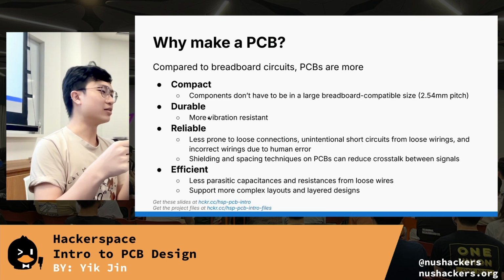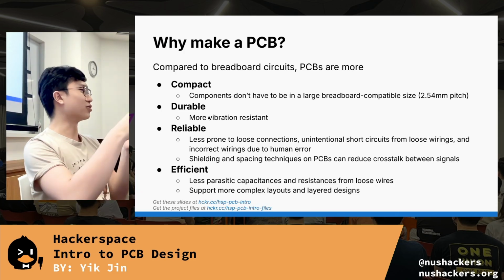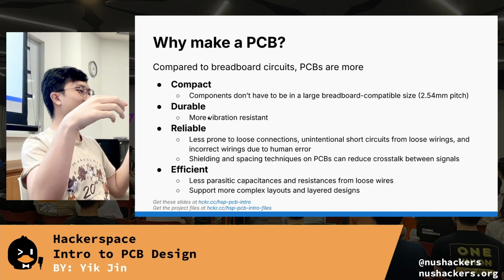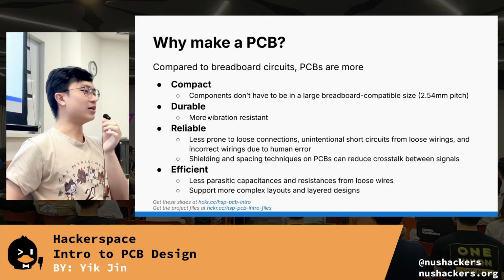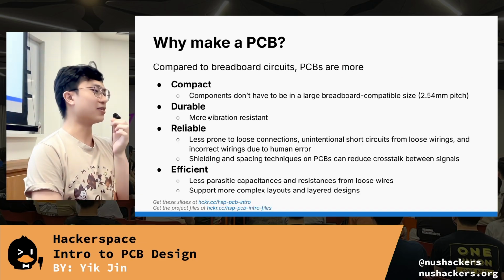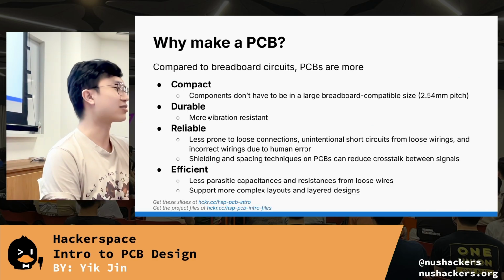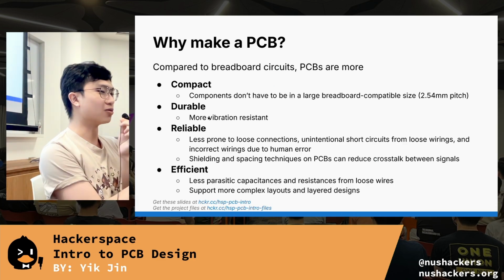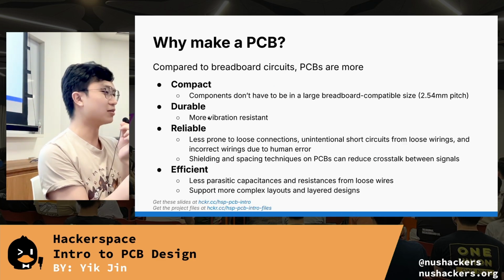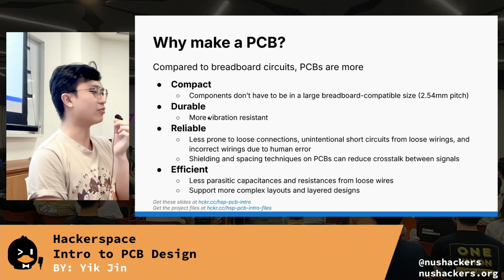The benefits compared to a breadboard circuit: if you're familiar with a breadboard, it's a white plastic thing with holes where you can prototype. The reason a PCB is better is, firstly, it's more compact, because it doesn't have to be in a breadboard footprint where each hole is 2.54 millimeters apart, which makes all your components very big. Secondly, it's more durable and more vibration resistant.